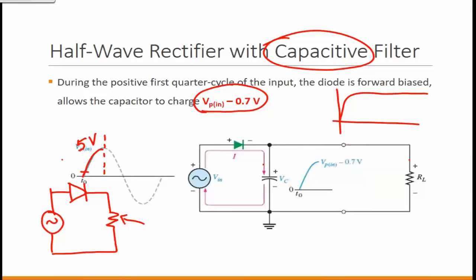When the capacitor charges initially, let's say it is holding that 4.3 volts, which is somewhere right here. Then immediately the signal voltage will start going down, correct? The capacitor plate right here is already held at 4.3 volts, because remember, a capacitor acts as a temporary battery which stores that 4.3 volts until it discharges, correct?